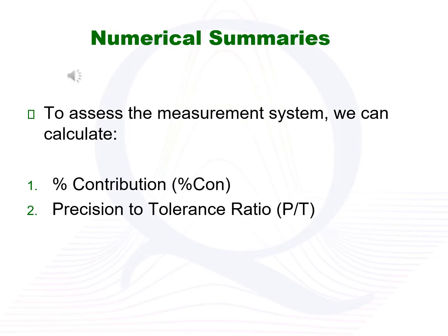For numerical summaries, we will look at the percentages each component makes up based on the overall variability. We will also see how much of the width of the specification the measurement variation takes up. Let's start with the percent contribution to the overall variability.